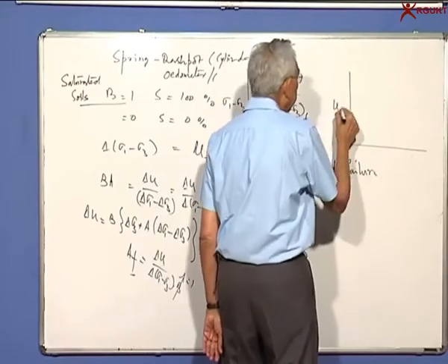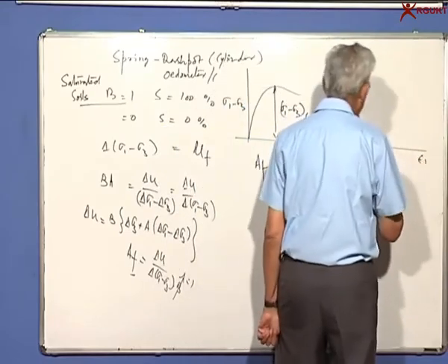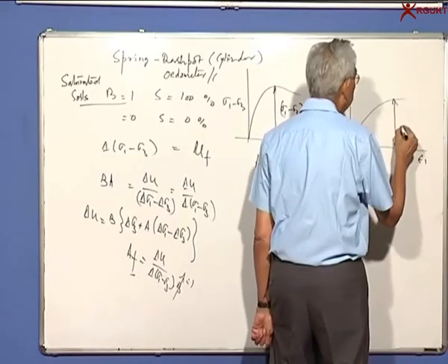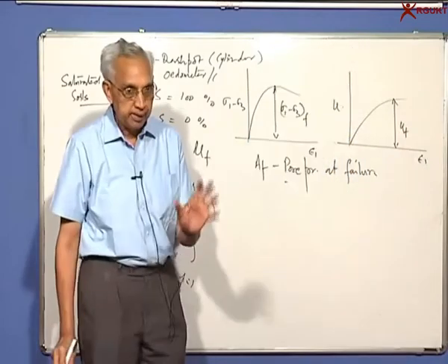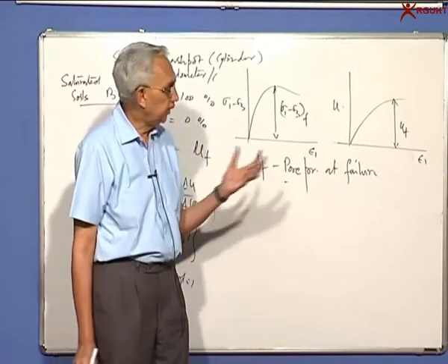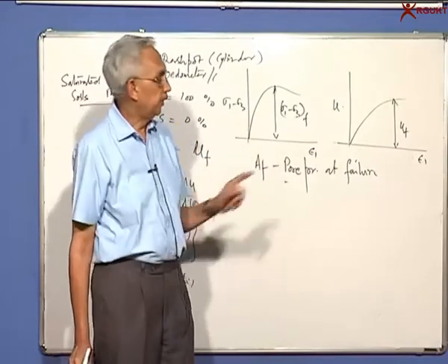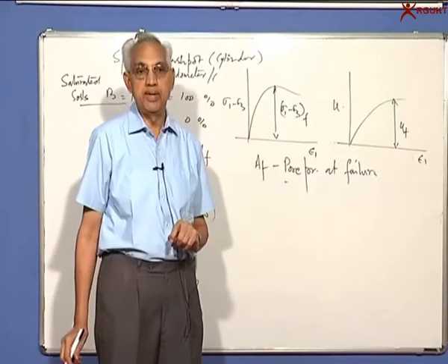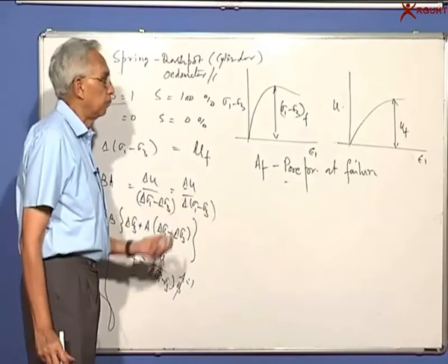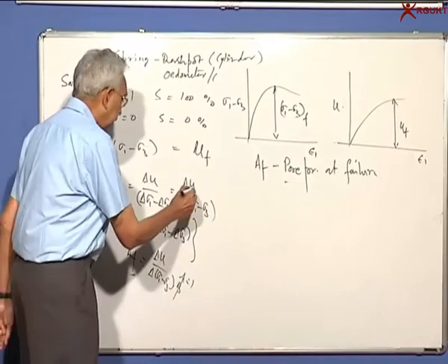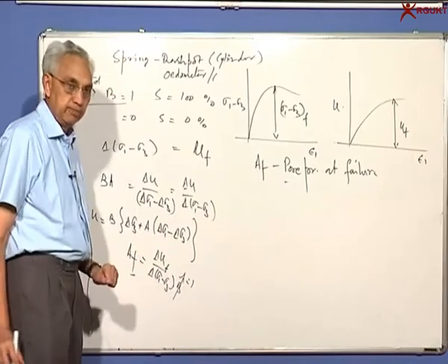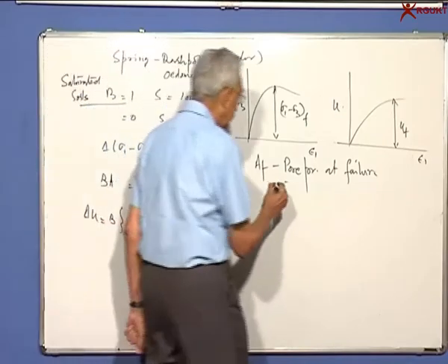Simultaneously, you are measuring pore pressure with strain, and you will find it may increase, and corresponding to that strain, this is UF. Pore pressure also increases as you increase the deviatoric stress. And then if I take the ratio, increase in pore pressure divided by the maximum deviatoric stress, I get AF. AF is a very sensitive parameter.